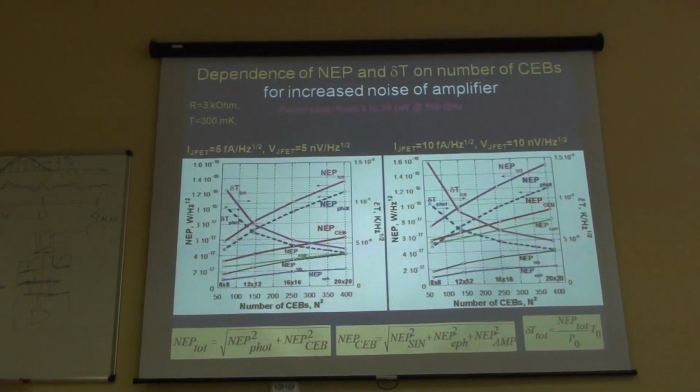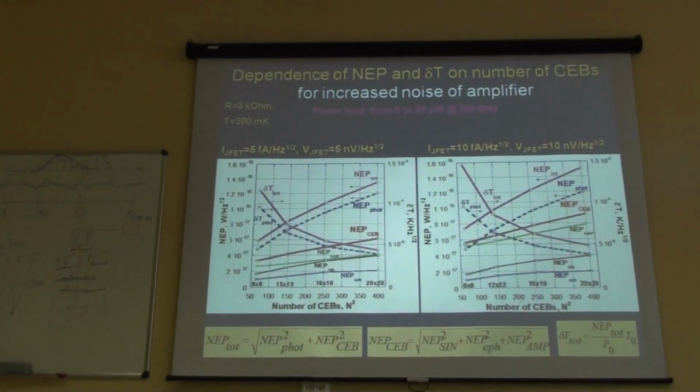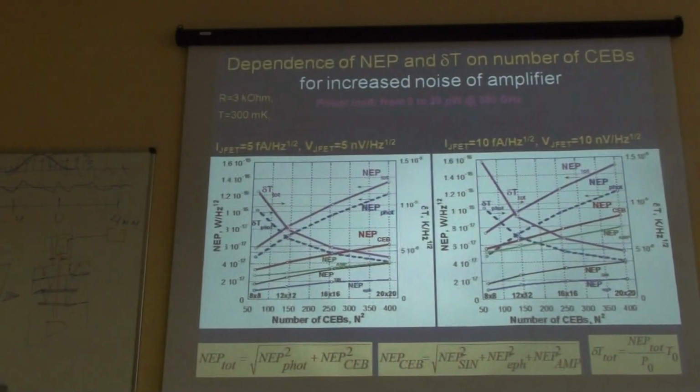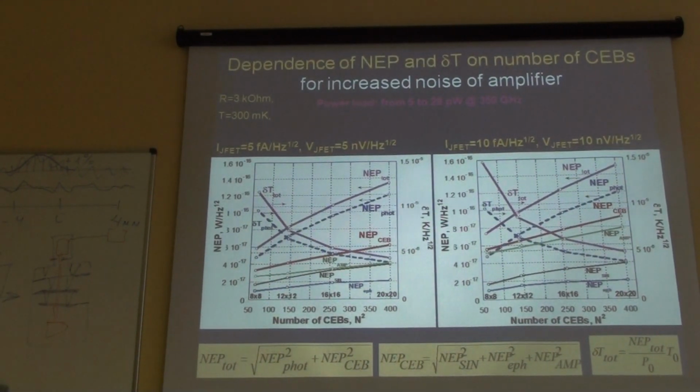When the whole team arrived, we scanned some gallium and so on with all the equipment. Yes, it should work. This is one good step in the direction. The second step will also be good: covering with silicon monoxide to do passivation for this anti-reflection coating. All the steps will improve reliability and yield. So let's hope it will be a good and reliable system.